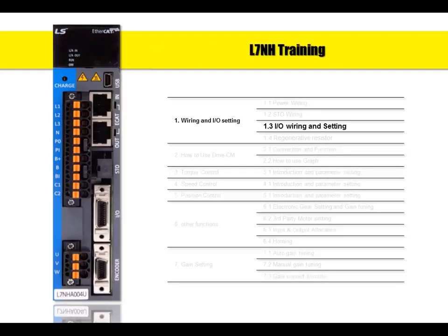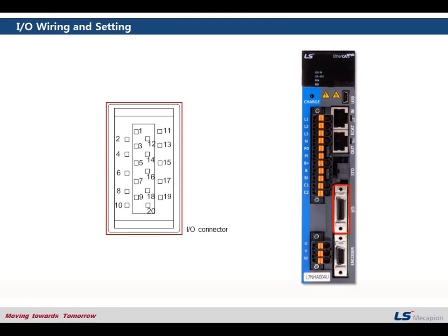Today we are going to learn about I/O wiring and setting. This is the I/O connector. In this connector there are 20 terminals. You can allocate input functions or output functions based on your preference.